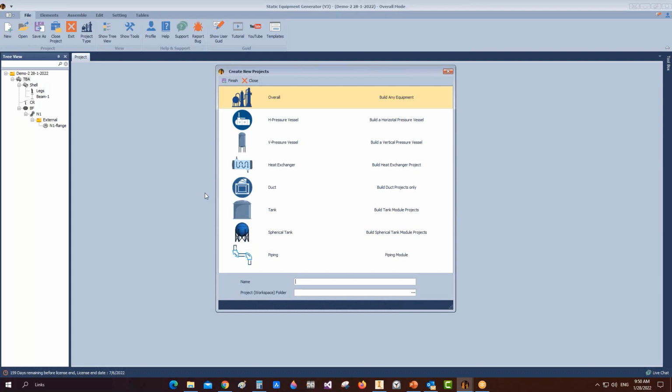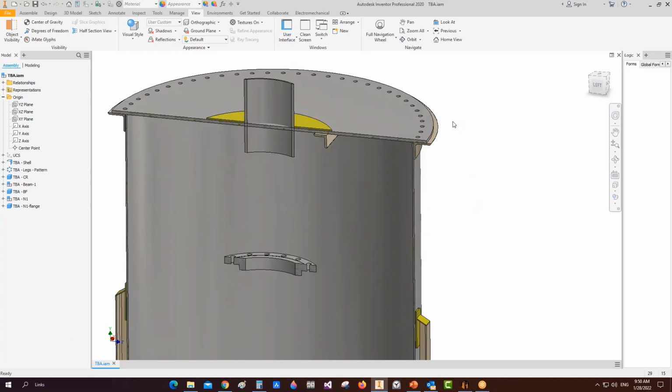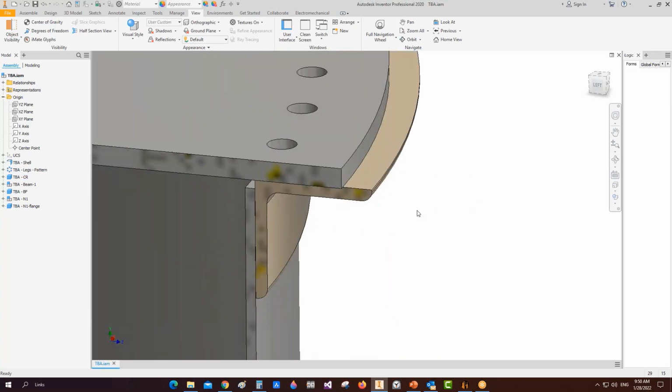Can you go to the model one time? I will repeat my question. You have a top flat, right? A top connection as a flat with the bolting connection, which we have given, and which is directly sitting on the angle, which we have given outside the shell. So we need to bolt it. These bolting holes we have to give in the angle. Is that possible? Because you have considered it as a compression ring, maybe you have to consider it as a ring.